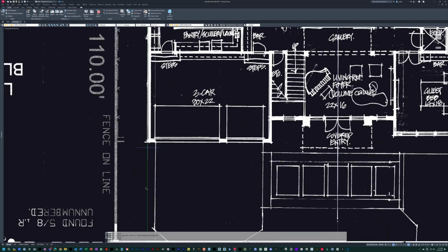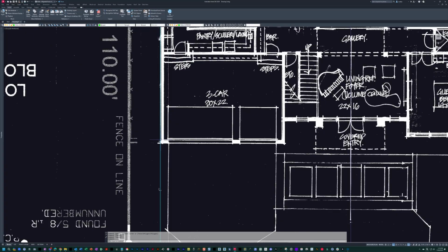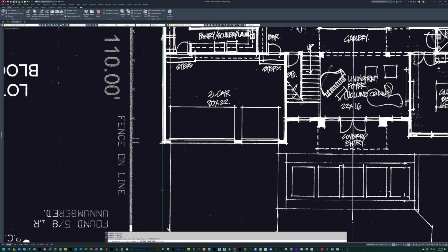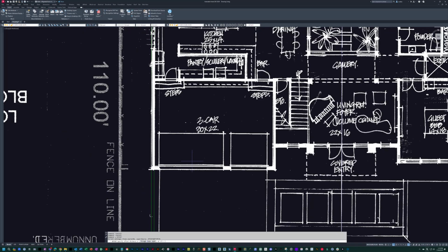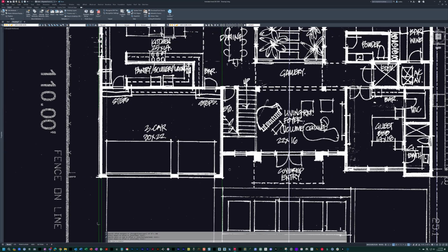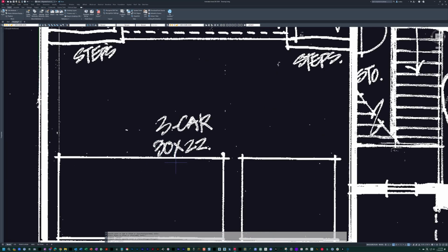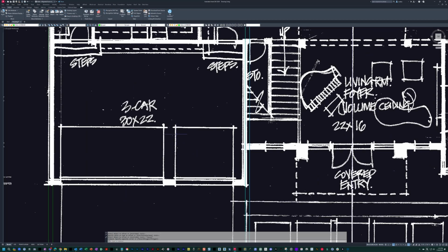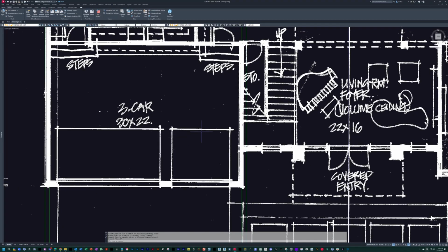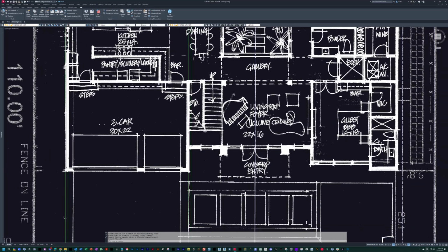So I have my green line. This is my wall exterior. I'm going to offset this 8 inches, and that's my 8-inch wall for my block wall working here in Florida. And then I'm going to offset this 360 inches for 30 feet. So that's what that is there. And offset another 8 inches. So you can see already it's not quite matching up to the sketch, which is fine. I mean, it's a sketch. This is why we're laying things out a little bit more directly.